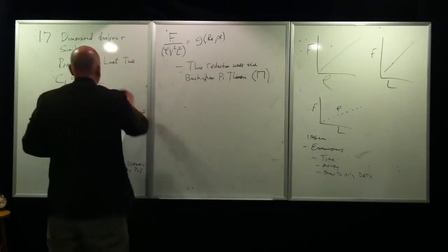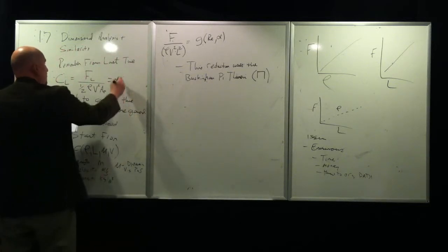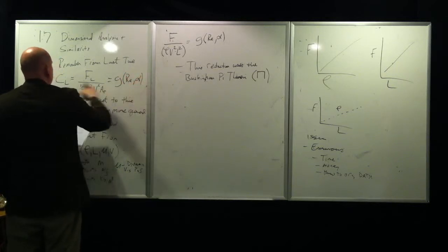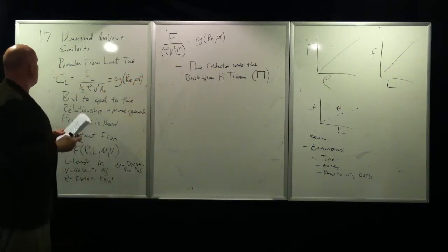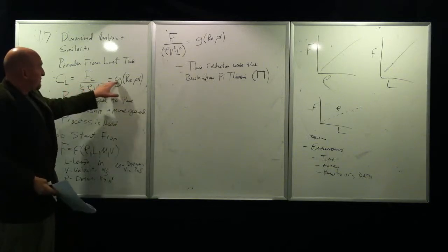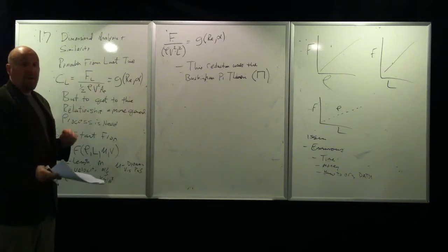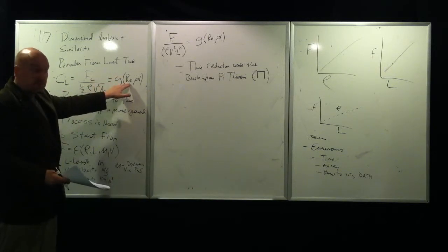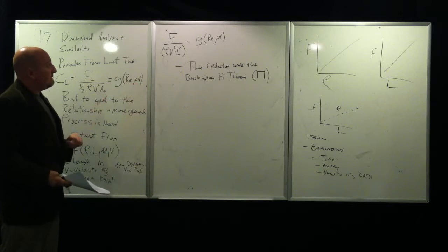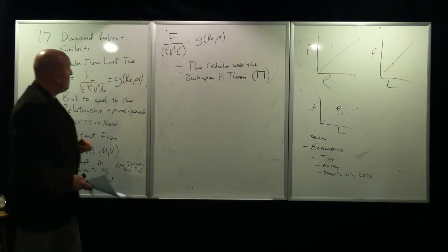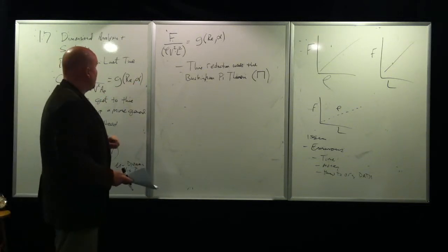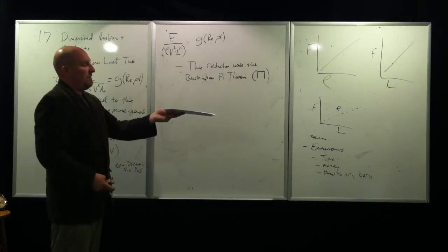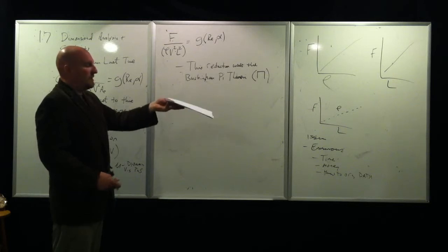So now we can say the coefficient of lift is really going to be some g function of Reynolds number and alpha. Coefficient of lift is just some sort of mathematical representation that varies with Reynolds number and angle of attack. We went over Reynolds number, rho v L divided by viscosity, and angle of attack, how the area of your wing is represented into the flow.